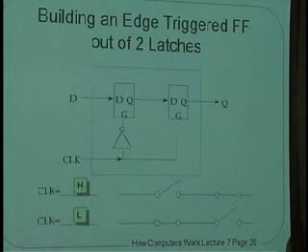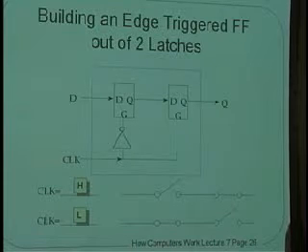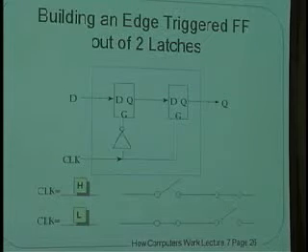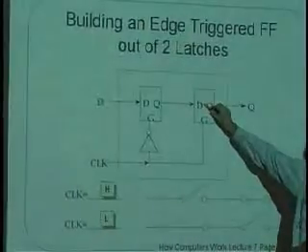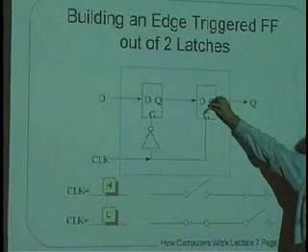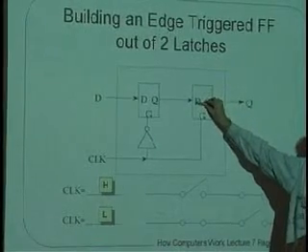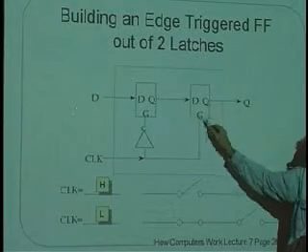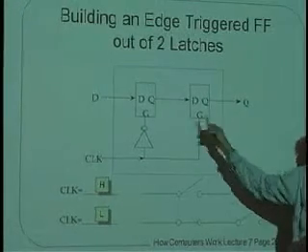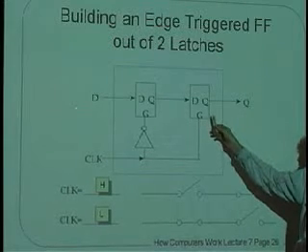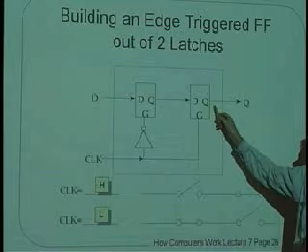Yeah? If you can do that on this, why couldn't you do it on the earlier one-to-one hazard state? Why do we need to build in the third AND gate? Because what you're talking about is the hazard that made it difficult to switch this thing here, right? We needed to do something when we were in the intermediate state. Okay, so what these circuits do when we're in the intermediate state where both G's are off is that they hold on to the old value there because they themselves are memory elements.